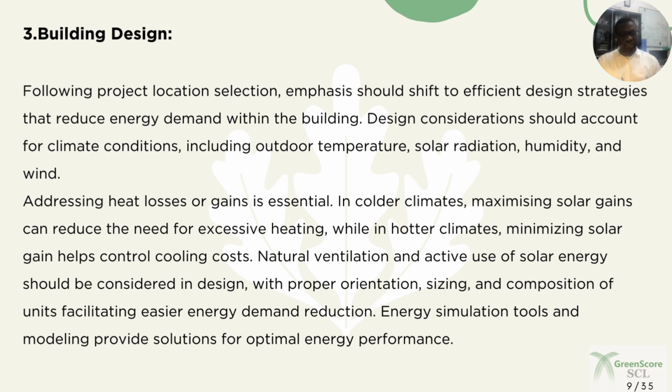And then natural ventilation also, an active use of renewable source, solar energy, should be considered in the design, taking advantage of proper orientation, sizing of fenestrations, and of course the composition of the unit, facilitating easier energy demand reduction.